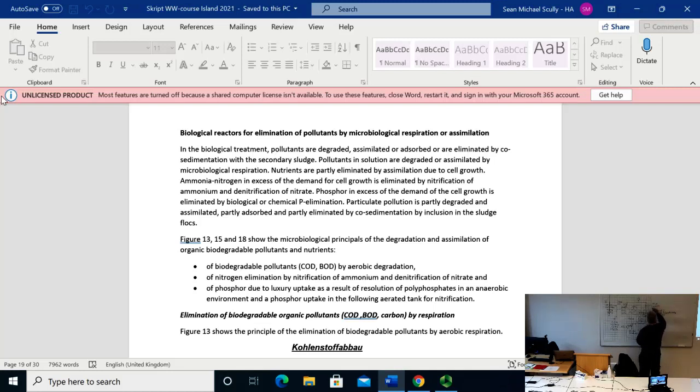In our effluent, we have 9.5 grams of total nitrogen. And from our phosphate, with 1.8, we have 1.6 minus 0.4, we have 1.2 grams of P per day. No? So we are fine with the COD, but we do have a problem with our nutrients. No?